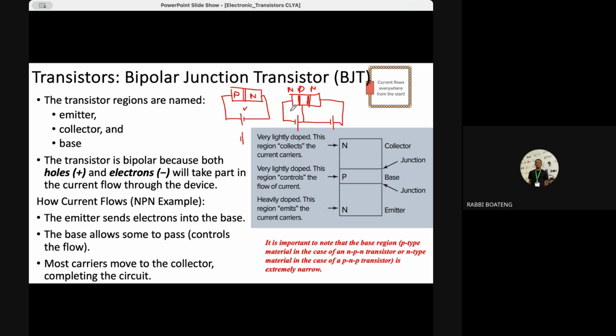Making this particular circuit a forward bias. Because when you look at this, it's two different circuits we've fused together. Is that okay? We want to look at it from two different perspectives. The first one here is going to be a forward bias, and the second one here is going to be a reverse bias. Because the N here is connected to the negative, and the P here is connected to the positive. Likewise, here, our negative is connected to the P and the positive is connected to the N, making this particular junction a reverse bias.